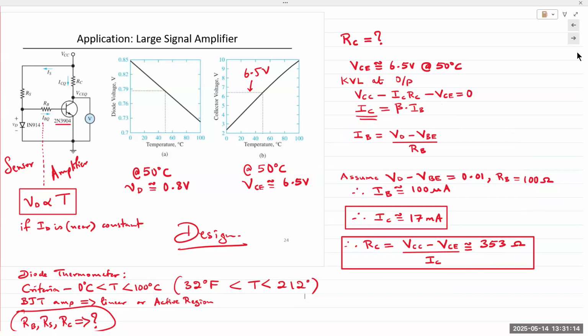So if we change the transistor, use the same model, 3904, but the beta is quite large, larger than the 40 that we are using in this circuit for this analysis, if it goes to like 75 or 80 or 100, then our IC is large. If IC is large, then VC goes into saturation. The BJT goes into saturation. It's no longer working as an amplifier. It's not in the active region anymore. So then this circuit would not work. Does everybody understand the point?